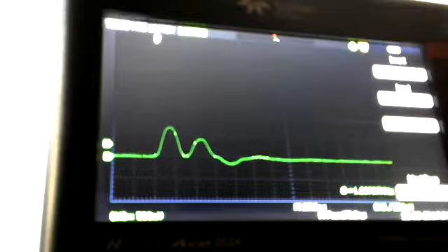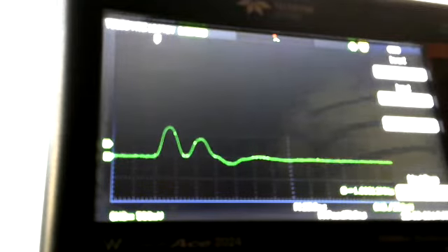But you see, it's become shorter because I've damaged the transmission line here. So now you have a reflection here, but it could have some transmission which would then reflect at this other end and give you a more complicated picture. But yeah, now it's permanently damaged at that point.